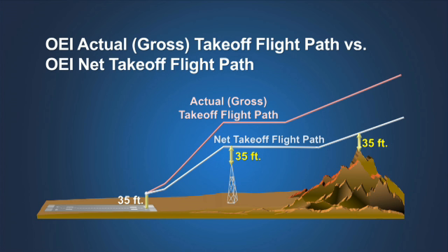These differences are due to the operational variations that can reasonably be expected in gross weight, thrust, airplane drag, pilot technique, wind effects, and so on. However, except during the level flight segment, there will be an increasing margin of obstacle clearance between the actual takeoff flight path following an engine failure and the net takeoff flight path used to assess the required obstacle clearance.